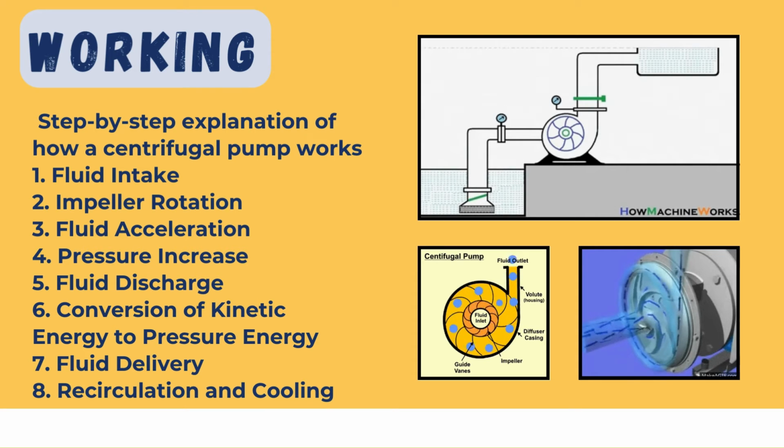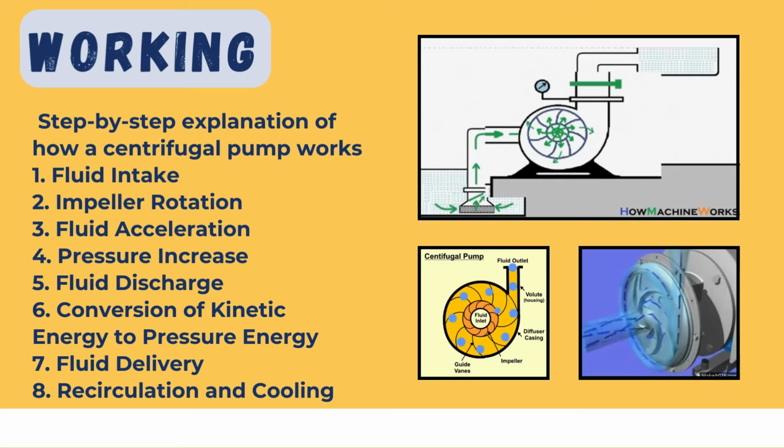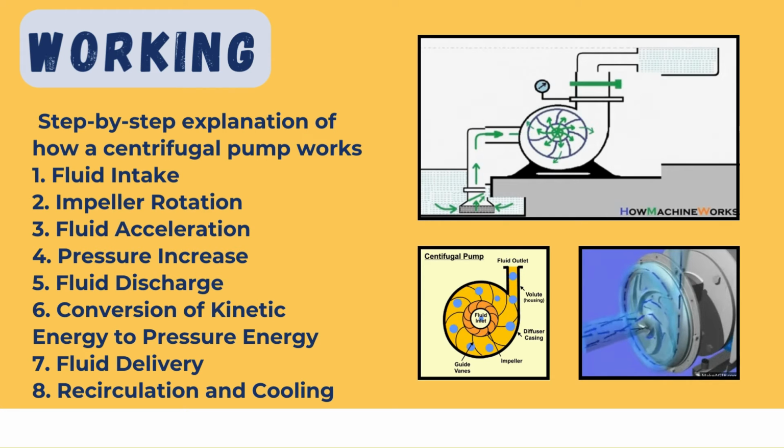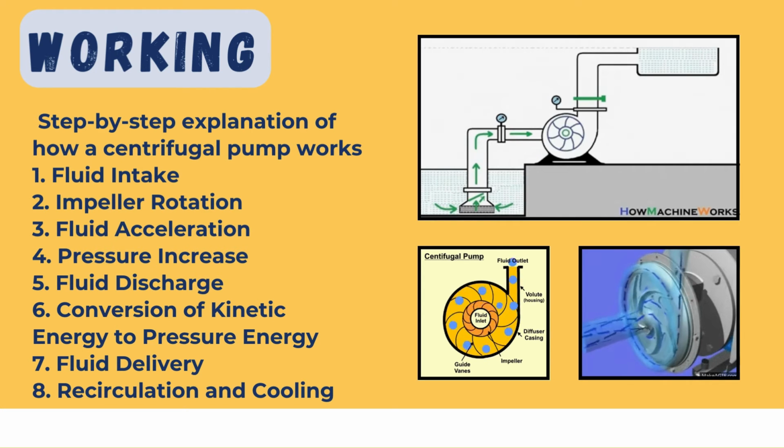Guys, here's a step-by-step explanation of how a centrifugal pump works. The working of a centrifugal pump starts with the fluid intake. The process begins when the fluid enters the pump through the suction inlet, which is located at the center of the impeller. This can be achieved through gravity, suction pressure, or external forces depending on the application.